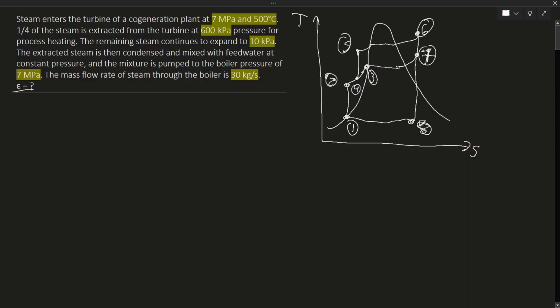All right, we have everything. Since there's no turbine efficiency, these are all straight lines. We know over here is constant pressure, constant pressure, constant pressure. Q out, over here Q in. This part over here is Q process. Work in over here, work in over here, over here, work out. Wherever you see vertical lines, it's work. Next, you're going to want to draw a table for yourself just so it's easier to keep track of all the enthalpies.